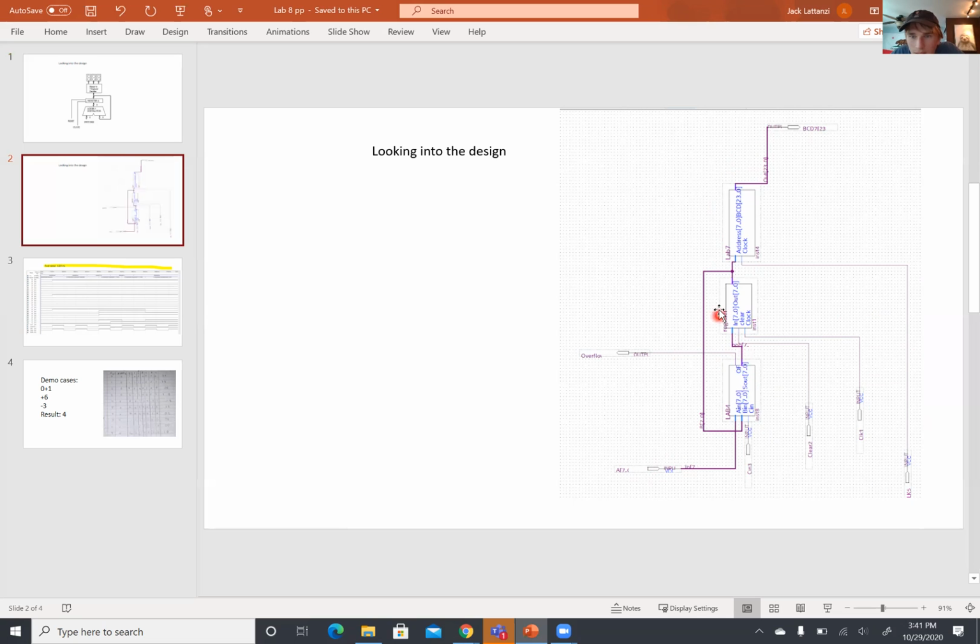It's added to nothing, goes through and it's stored here, comes out, it's displayed. The address line comes in here and the address is found here, and this corresponds to the 24-bit output, which 7 or 21 of them are used in the display and there's 3 padding bits. There is also the clear function here, which will clear the register and the whole system, which is stored in here.